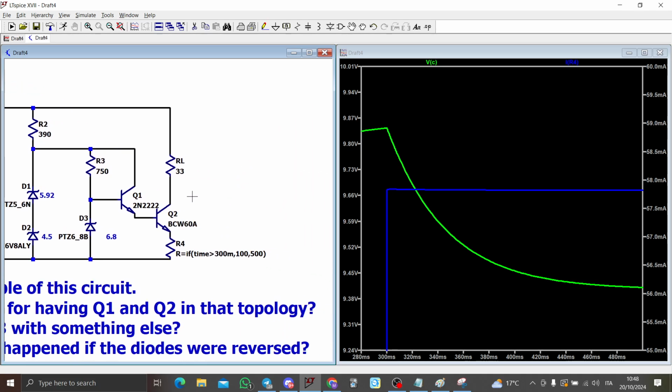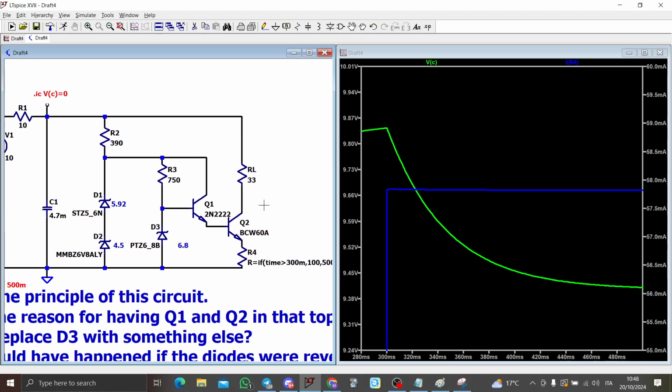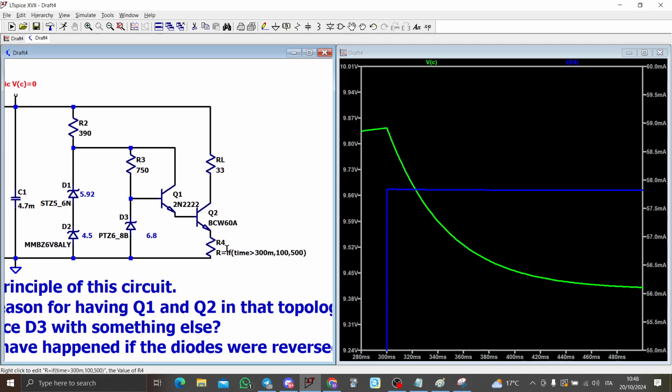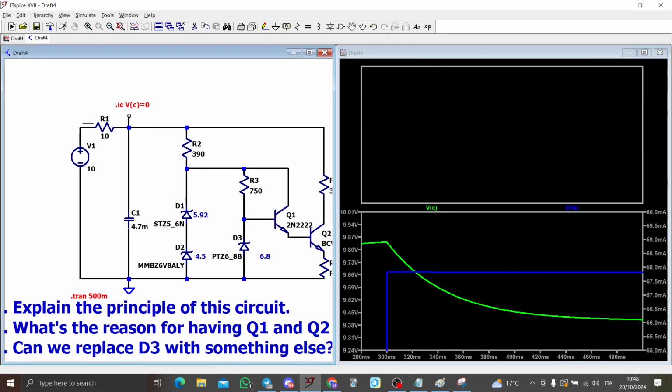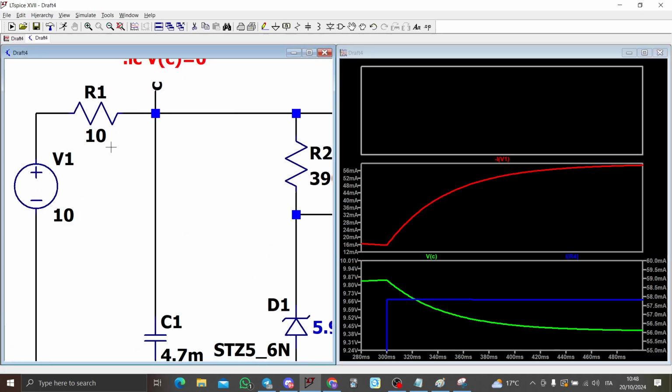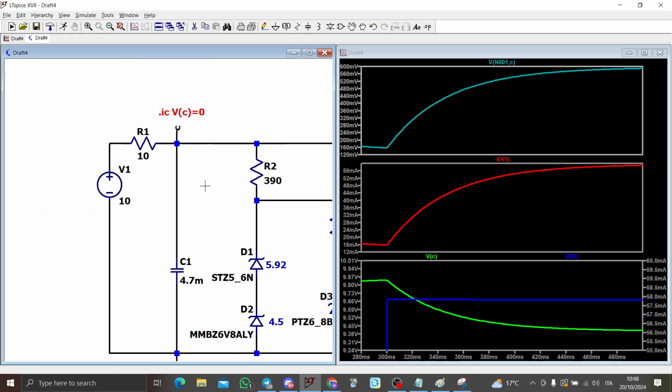Naturally, this capacitor here should block just a pulse current. This is permanent. Okay, this is a permanent load. So it is normal that you have a permanent drop voltage here because you're asking a current of 56 milliamps, which results in a permanent drop voltage of 600 millivolts. So it is also important to make this kind of analysis.